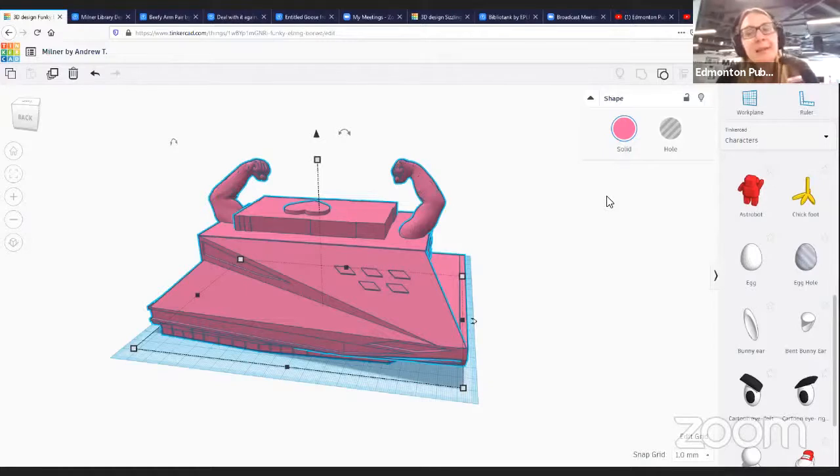Sometimes they're set up so that they give you warnings, or sometimes the software that Jermaine and I looked at earlier with the whale will give you warnings about this. But sometimes what can happen is, with some software or some situations, pieces of the face of each triangle that goes into the polygons that make up this object, sometimes the triangle might be missing, sometimes it might be facing the wrong way, sometimes it could be intersecting with another triangle.